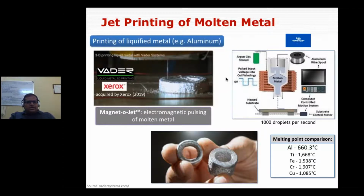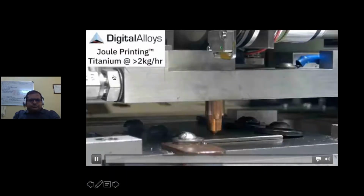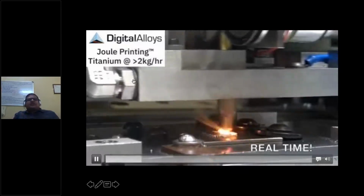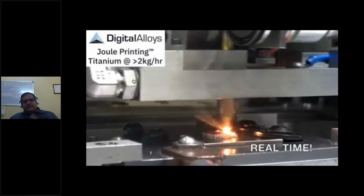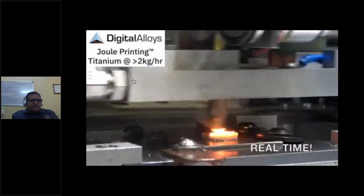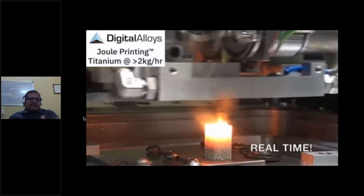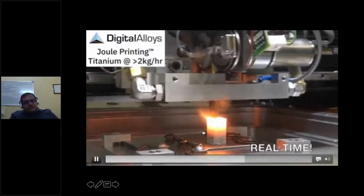There is another similar technology called Joule printing, where, in real time, it's very fast, it may be more than 2 kg per hour. So you can target it at DED systems. DED or welding technologies have very low speed, as does a powder bed, but this is much faster. It may almost compete with conventional welding processes like TIG or MIG welding. That is the beauty of this technology, Joule printing.